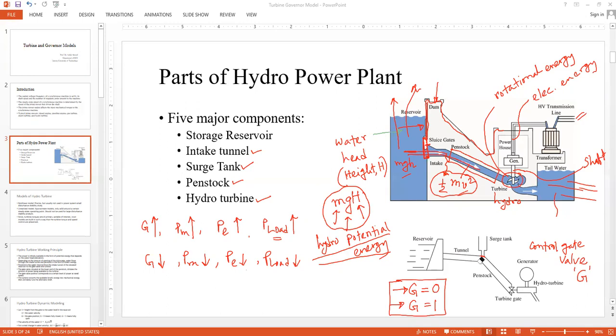So this is also known as water hammering in short, as if you are hammering the walls of the penstock with the help of the water. So to get rid of the water hammering and to increase the life of whatever structure you have built, you will allow the additional water, the pressure that is being exerted by this closing of the gate valve.